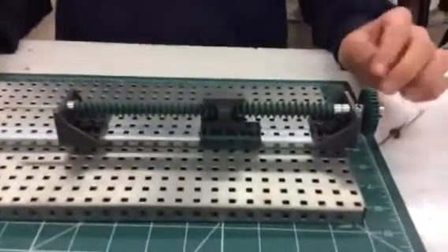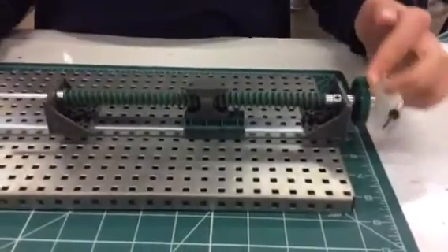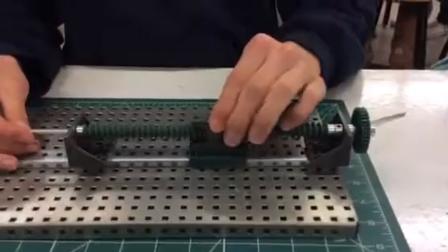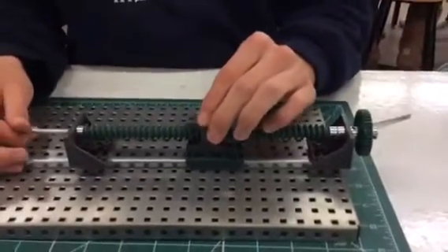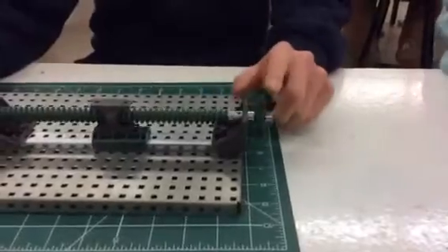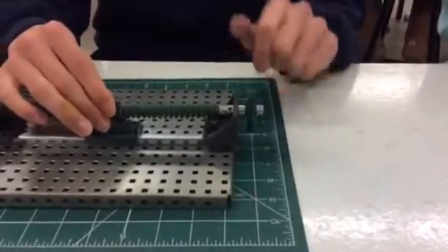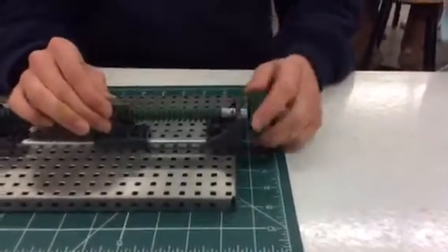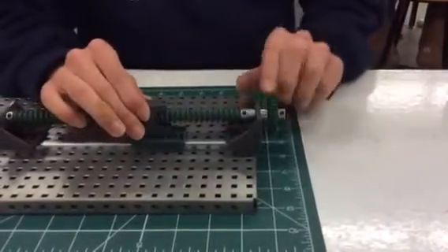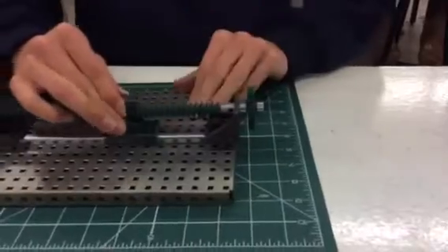I'm Alex. I'm Ryan. I'm Riley. And our mechanism is the lead screw. Our input movement is rotary because the screw moves in rotation. And our output is linear because the shuttle moves in a straight line. Our direction of travel is reversible. The shuttle can go left and right. And our flow of power is not reversible because I can't move the screw using the shuttle.